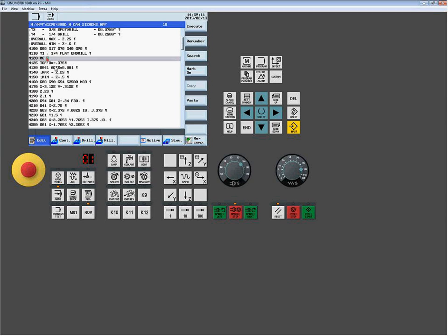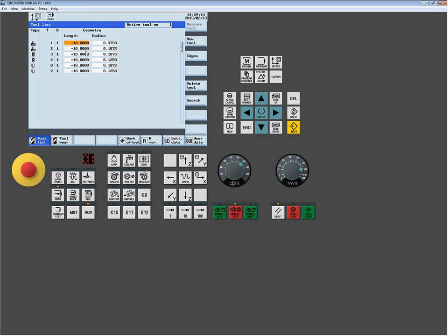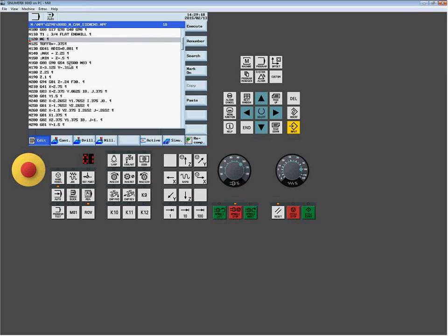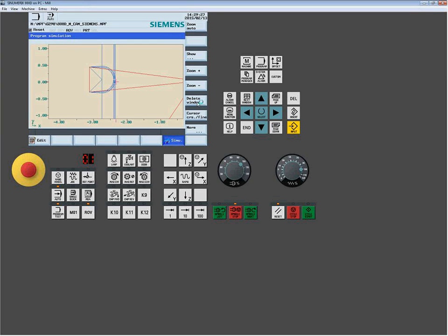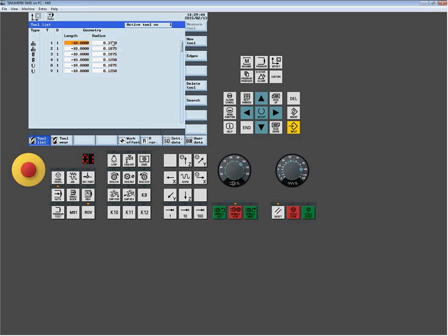What that's doing is it's saying, okay, I understand I got a 3S tool, but in reality, I'm going to take that 3S away before I run the cutter path, but you still have cutter compensation. So if I simulate that same part program, I'm going to delete the window so we'll get a fresh simulation. The same results as I would have had before. Not getting double compensation. This part would have been at 2 inch. That's correct. Now I can just add, subtract to the diameter like a real scenario.